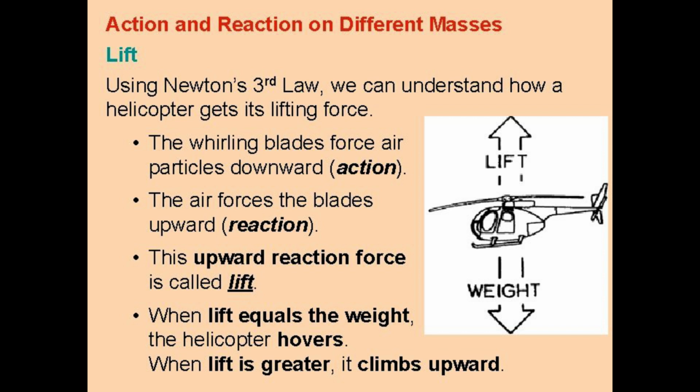Since air is much like water, the explanation for this source of lift may be compared to the planing effect of skis on water. The lift that supports the water skis, and the skier, is the force caused by the impact pressure and the deflection of water from the lower surfaces of the skis. Under most flying conditions, the impact pressure and the deflection of air from the lower surface of the rotor blade provides a comparatively small percentage of the total lift. The majority of lift is the result of decreased pressure above the blade, rather than the increased pressure below it.